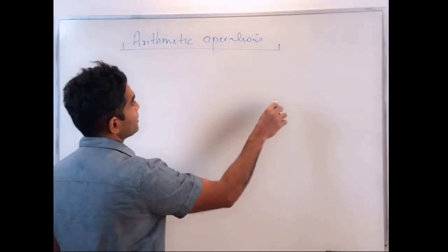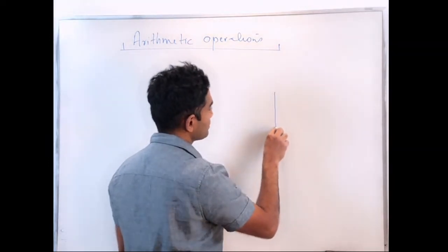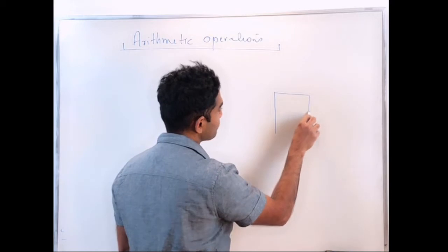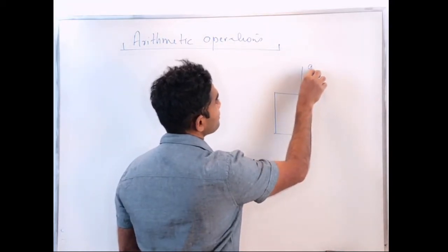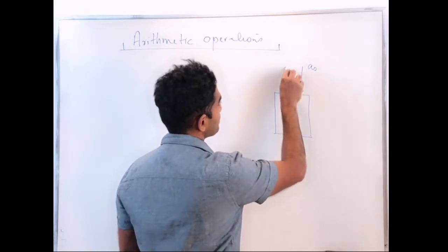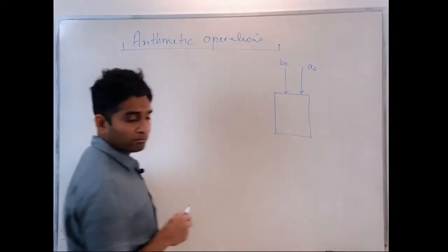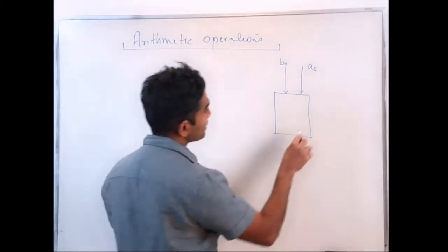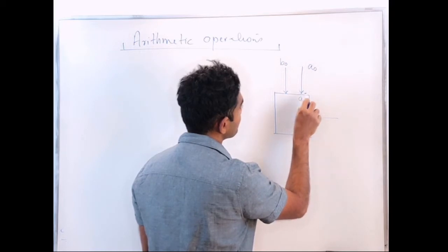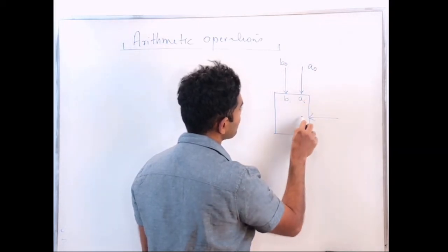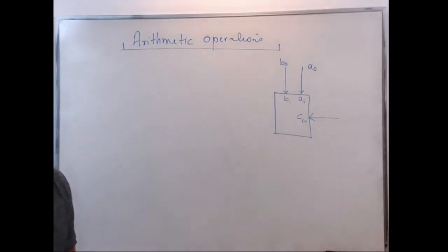So now I want to build an n-bit adder, so I will use that module. It takes in, at every bit position, those corresponding bits, Ai and Bi, along with the previous carry, Ci minus 1. Those are the three inputs to that module.